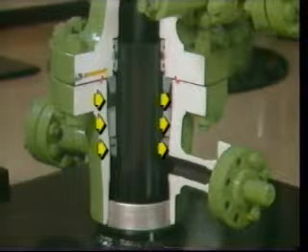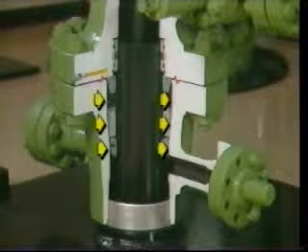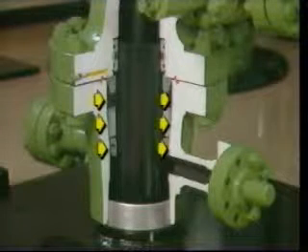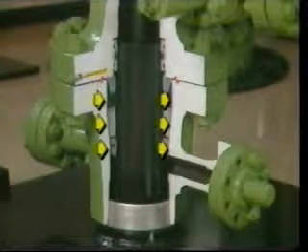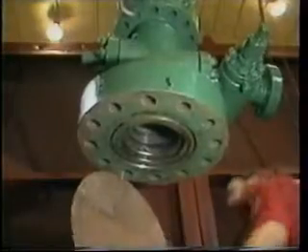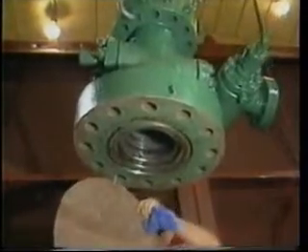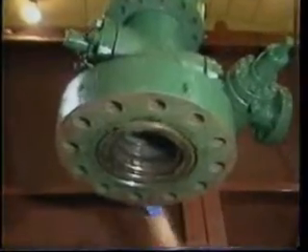Casing bowls are of two basic designs. One design carries the load of the casing on a load shoulder. The seal area is a vertical metal-to-metal contact area. The other common bowl design offers a tapered seal area, which acts as the seal and carries the load. Metal-to-metal seals are preferred for high-pressure and corrosive environments.